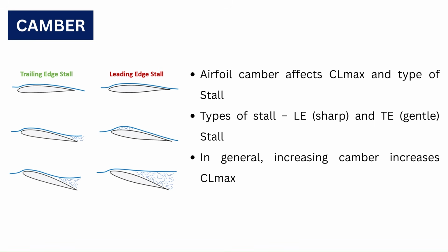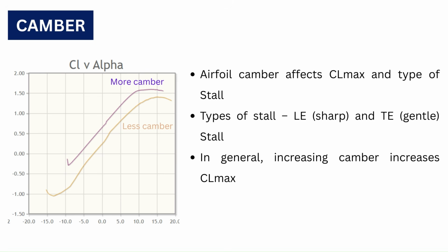How the airfoil is cambered affects its maximum lift coefficient and the type of stall it has. We have already discussed the two types of stall patterns in the previous video. In general, increasing the camber increases the maximum lift coefficient the airfoil will generate. Of course, this applies to a certain limit.